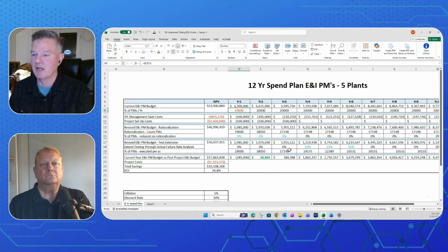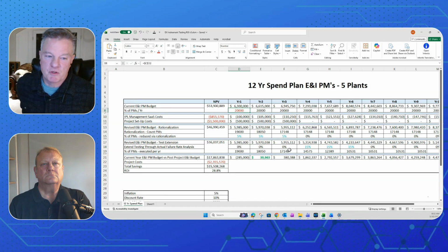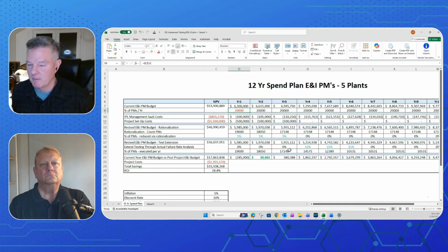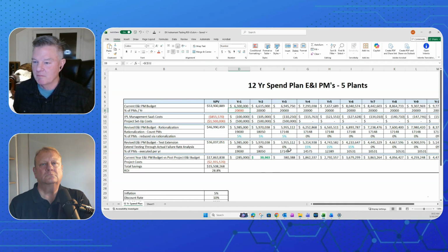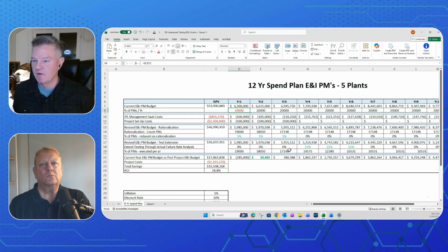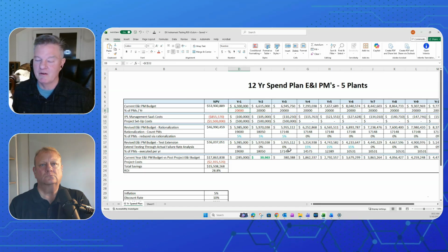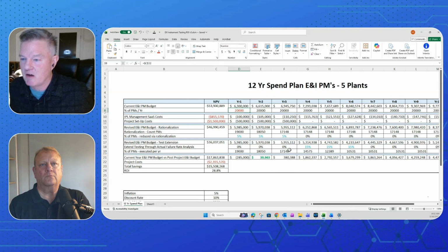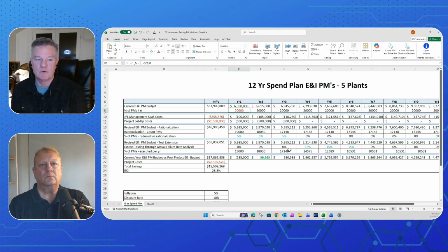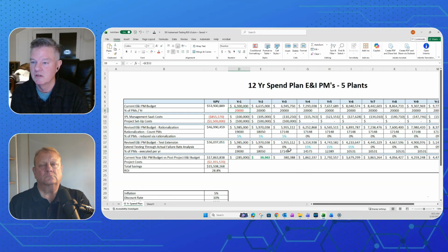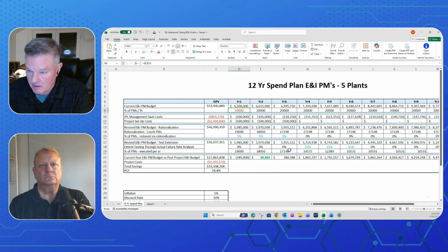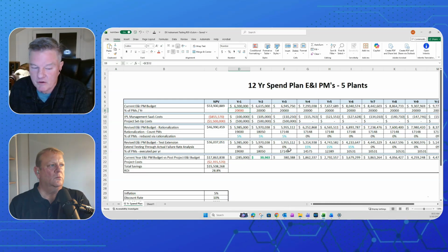So for instance, if we're checking for plugged taps and we pump up the transmitter with a pressure source, and when we're done, we open up the root valve and we equalize pressure, we're blowing down that tap. So you're getting testing benefits every time we test. So if we go from annual testing to once every 20 years, we might see 90% of our stuff with plugged taps in that service because we didn't think about the testing benefits. Same thing with a valve in nasty fouling service. If you're doing a full stroke of a valve annually, well, you're cleaning seats. If we go straight to 20 years with it, you might have valves concreted and gunked up such that they can't close fully, and now you're screwed and you've got a hazard.